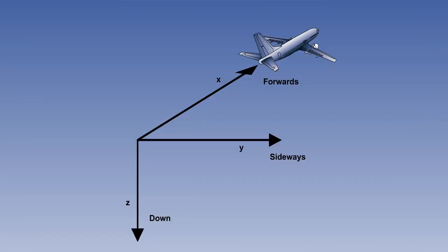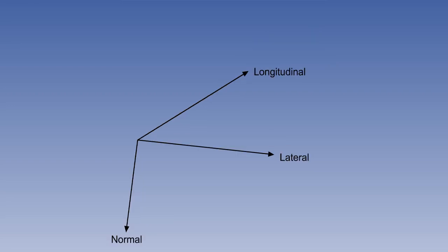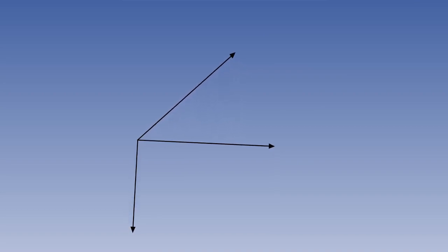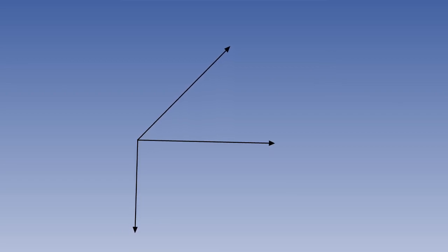Let's summarize the main points from this lesson. There is no gyro-stabilized platform in IRS. Instead, the gyros and accelerometers are fixed to the longitudinal, lateral and normal axes of the aircraft, and they maneuver with it. This is known as a strapdown system. Conversion of longitudinal, lateral and normal axes of the aircraft into the directions of north, east and earth vertical is carried out by a process of mathematical modelling known as axis transformation.